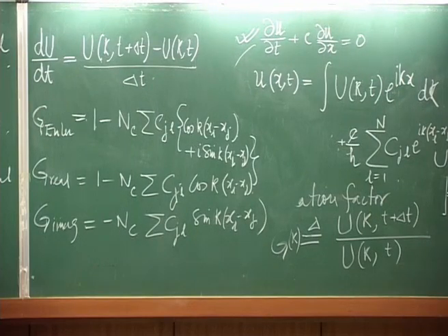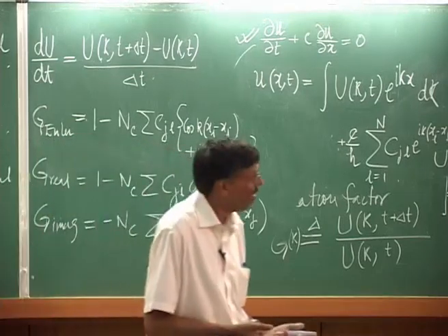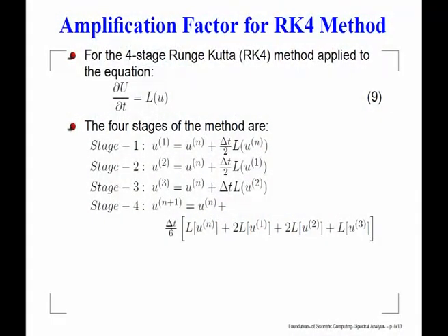time integration very undesirable. It will lead to instability. Okay. So, this is that. So, what are the other better methods that we have? And let me tell you, for some of the time integration methods that we have investigated, we have developed ourselves, we find this is a prime candidate which gives excellent property, and this is your 4-stage 2-time level Runge-Kutta method.